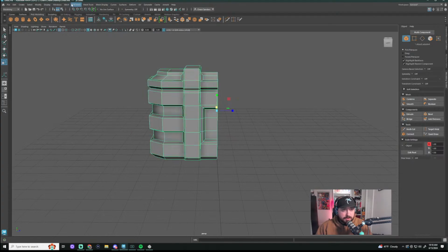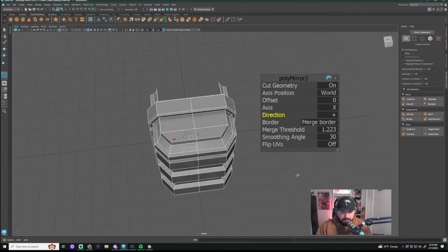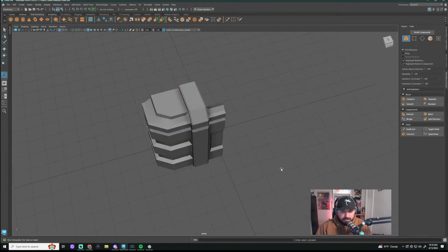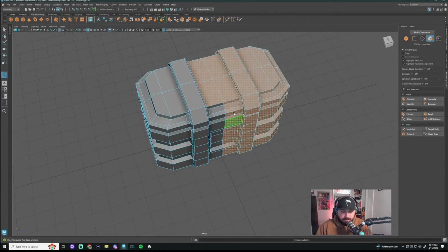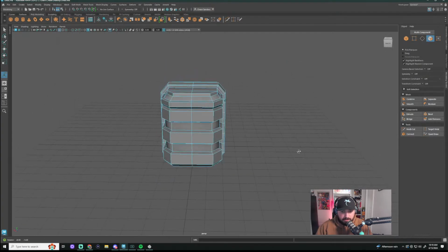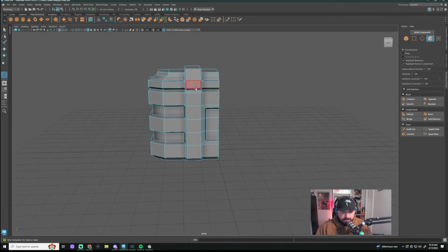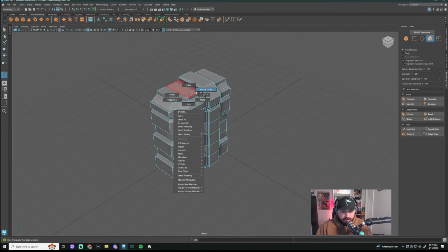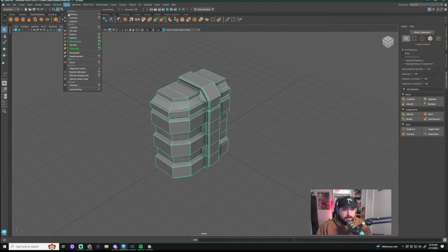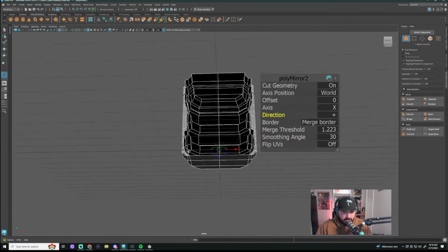So we'll go mesh mirror. And in the X positive, we'll mirror it, right? Actually, I think I deleted some extra faces that I didn't want to delete. So let's double check. So we'll try that one more time. I fixed that one. So this is here, object mode, mesh mirror in the positive X so that it goes backwards.